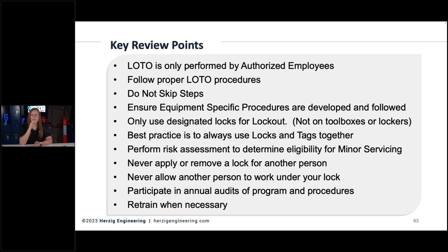There's some nuance there. Never apply or remove a lock for another person. In our electrical safety training, we have an example of this, a story from a gentleman talking about his experience being in an arc flash. He was trained wrong because his mentor locked it out for him, and was more focused on teaching him how to do that task. So whenever he went back to do the task again, he didn't know that he had to lock it out himself. He thought, well, I was assigned this task, it must already be locked out because that's what happened last time.